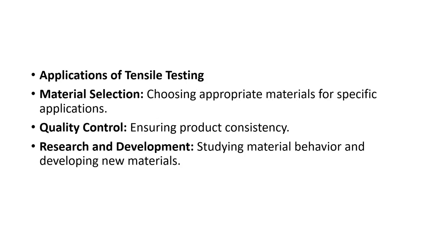Various applications of tensile testing. Tensile testing is very important because a design engineer wants the ready-made tensile strength of material, which is given in the design data book. The first application is material selection, which is normally part of the design engineer's work in any organization: choosing the appropriate material for a specific application.